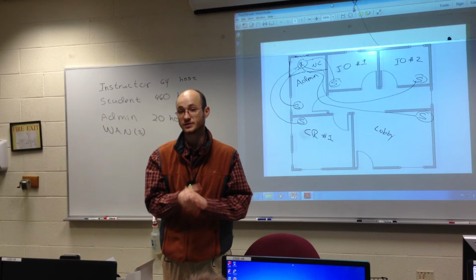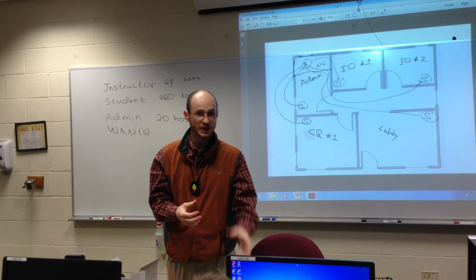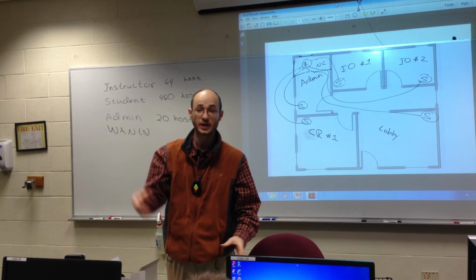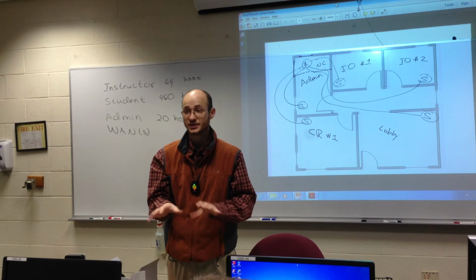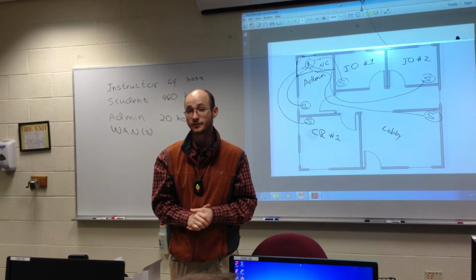You just run your hands in a bunch of soap as you're pulling it, and you usually have 2 people, one person at the box and the other person at the far end trying to pull the cable as it goes. The person near the box is just putting their hands in soapy water, and they're just running it up and down the cable as they're pulling it.